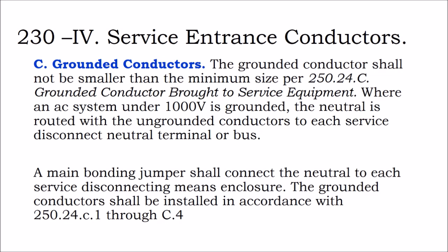And if that happens to be your main service panel, maybe you have a combination meter base where the meter is inside the service panel and that's the only service panel for the entire system. Well, that might be the utility service disconnect, but your main service panel is not always considered by the utility service to be the disconnect. Often it will be inside the disconnecting means enclosure, which might be the meter base.